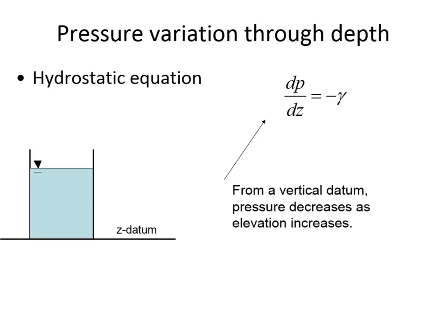So we can think about it that the pressure is going down as elevation goes up, or if we're at the surface, if we're at the top, then the pressure at the surface, I alluded to this in our last class period, if it's open to the atmosphere, so if it's got the little triangle and these hatch marks, that tells us that there's air and that it's not sealed off. So if it's open to the air, then the water at the interface has the same pressure as the air immediately above it.